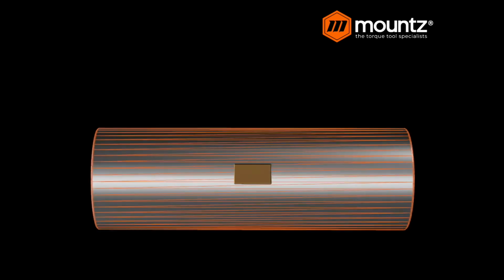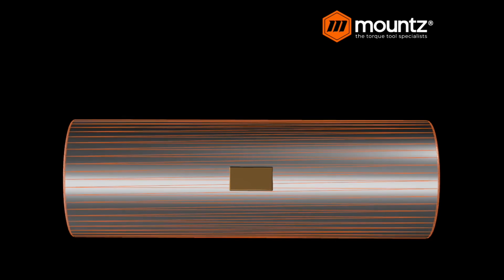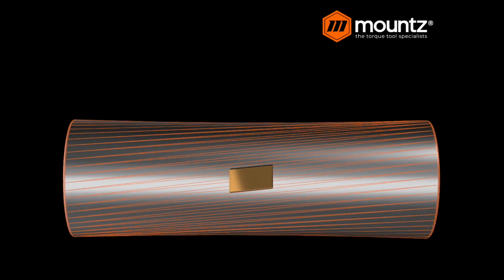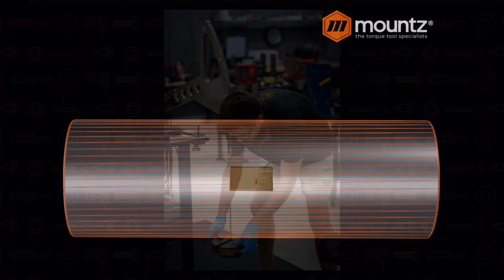So we have our strain gauge that's laminated to our stock. And then as the stock turns or tension is applied, the strain gauge will flex with that as well, again changing the resistance level and giving us our ability to see what the resistance change is from the standing state to a torsional state.